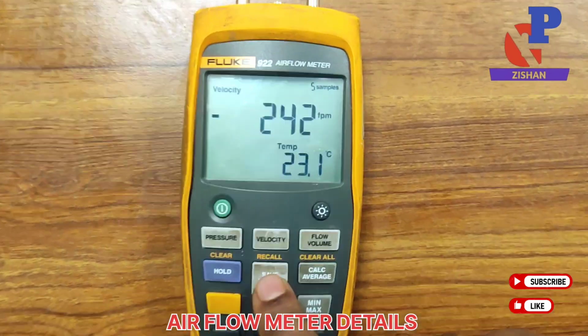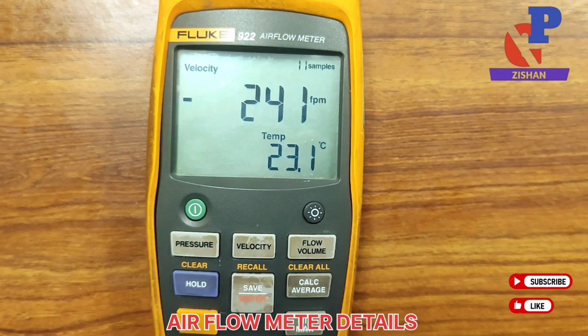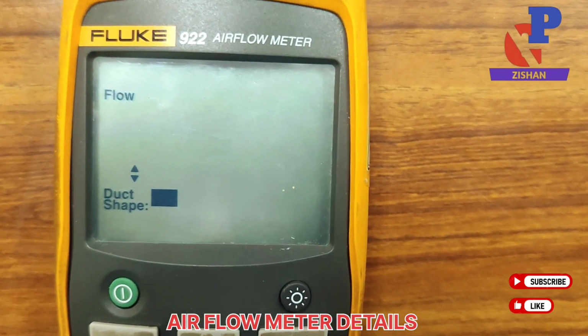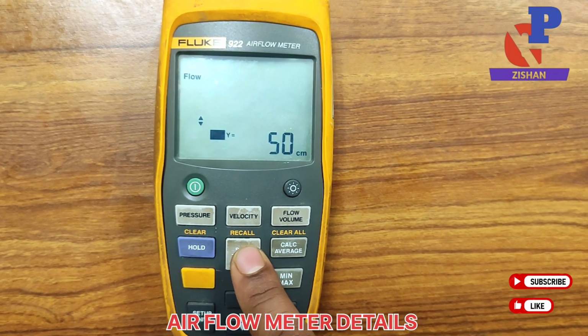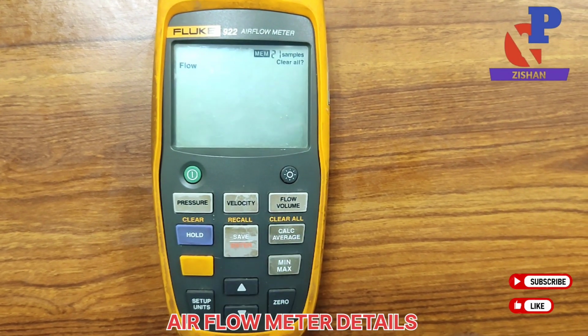For the velocity we take different samples by pressing the save or enter button. For the flow volumes there are two options, either the duct is rectangular or circular. According to your duct we can take the flow volume, and it gives you the CFM value directly.